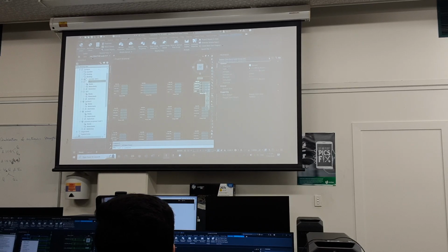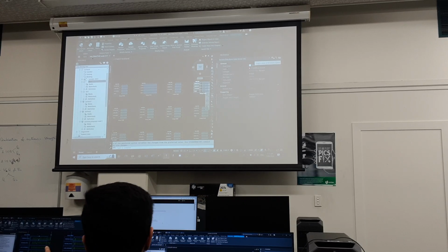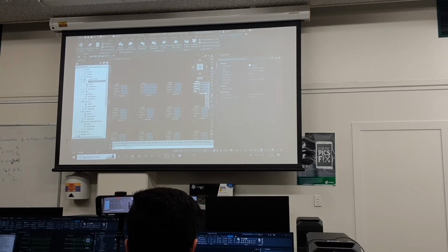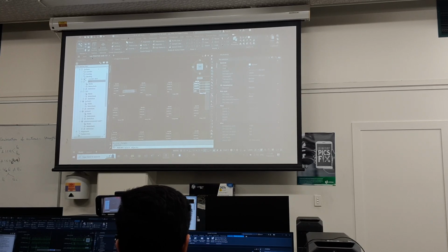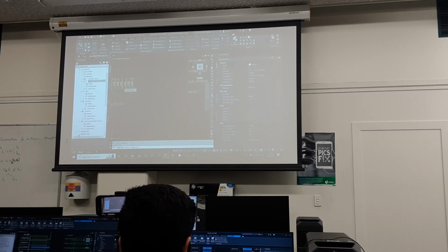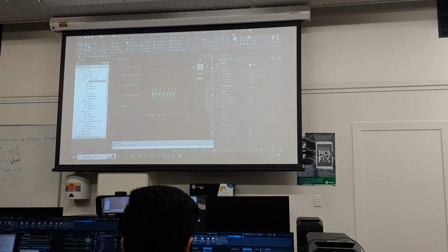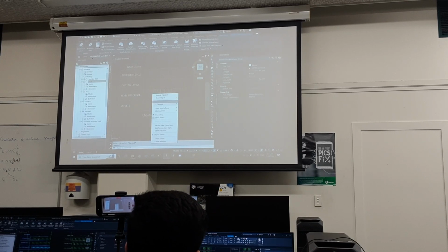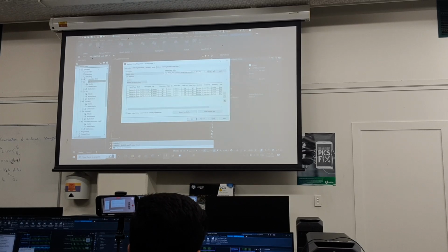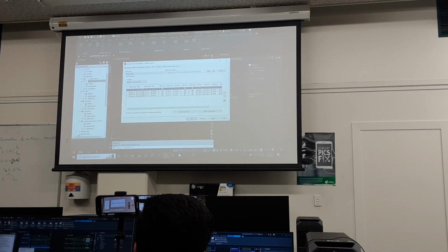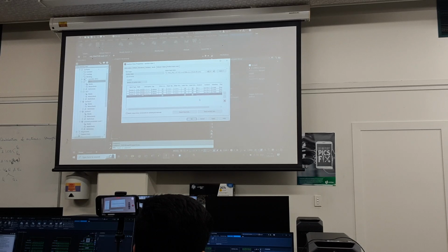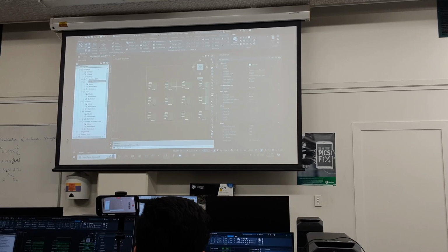Let's make another one here. Is that an assembly? Alright, sample lines. We should be able to set these earlier in section views. The grunt way of doing it is just editing every one. If I click on one and right click and go section view properties, data and bands, I have to go through data and bands and change each one to automatic. It doesn't take that long, but it's annoying. There's got to be a better way of doing this. If someone can figure it out, please do. How do you do it?